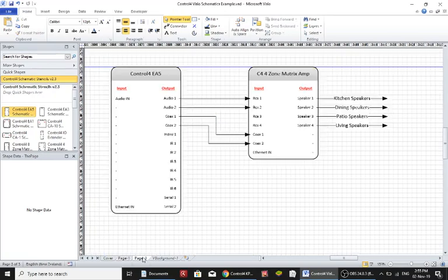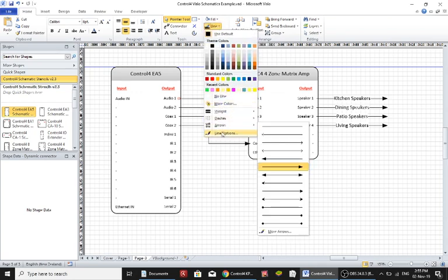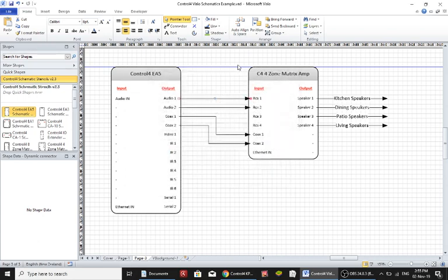Now while we're at it, I'll show you a very basic drawing that I've just done, and I have some items called line ends. Now I'll show you what line ends are. So if you look at these lines, you'll see that there is an arrow on the end, and that is just using this feature up here under line options, and you have line ends. Now what I've actually created is some line ends that look like RCA leads. Now I'll show you how we apply those.